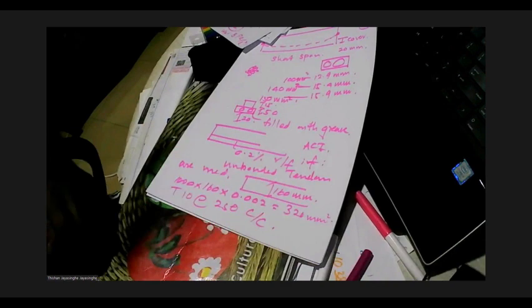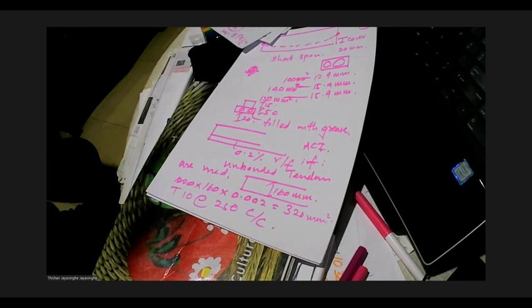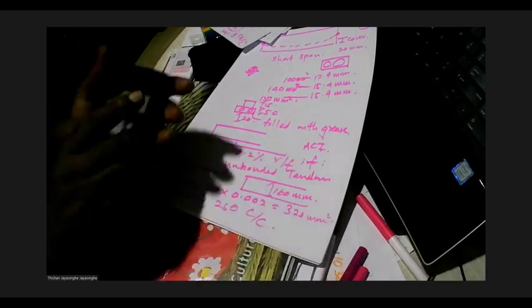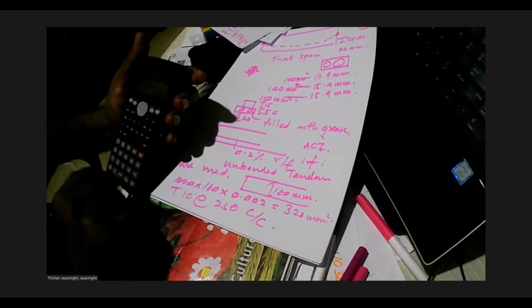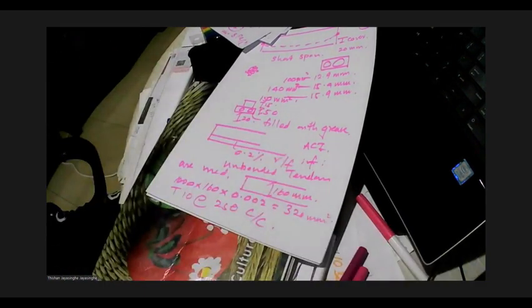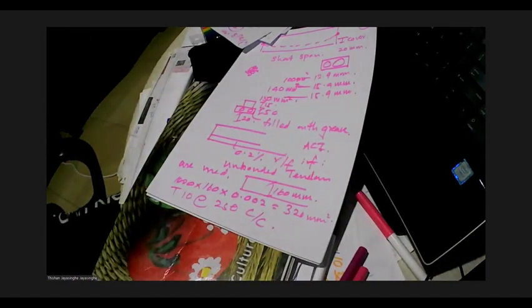T10 at 250, center to center. With 160 millimeters, you can go for about 6 meter spans. So you say it is about 6.5, about 7 meter spans, you can use 160 millimeters. For 7 meter spans, generally you need about 170, 180 millimeter slab. So here you get a 160 millimeter slab.